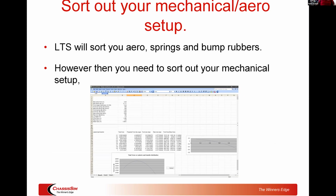The first thing to do with the simulation approach, step 1, is you sort out your mechanical and aero setup. Now, the great thing about the lap time simulation is it'll allow you to sort out things like your aero, springs, bump rubbers, ride heights, gear ratios.